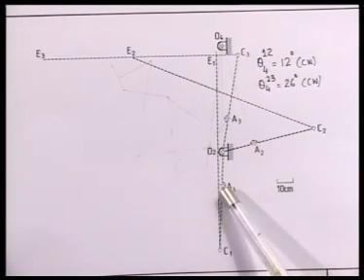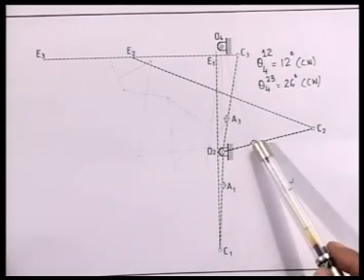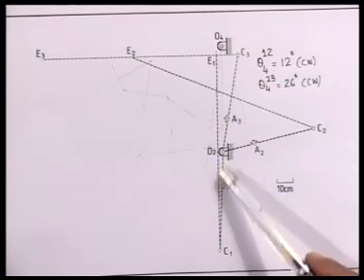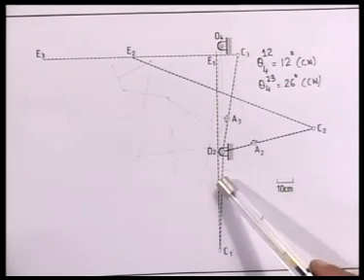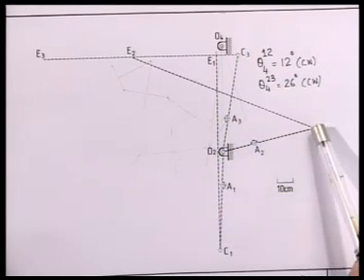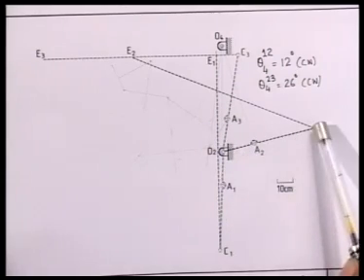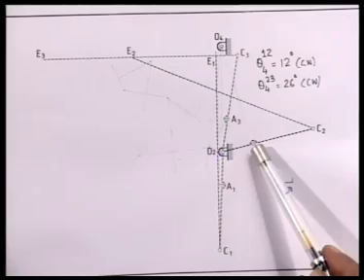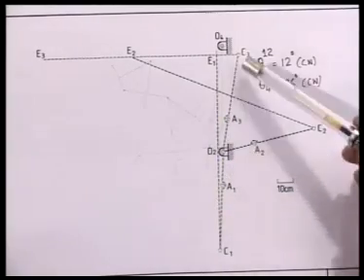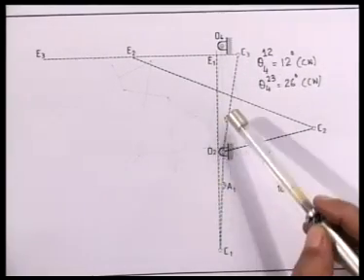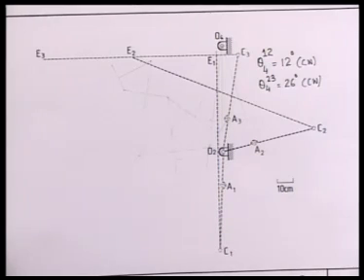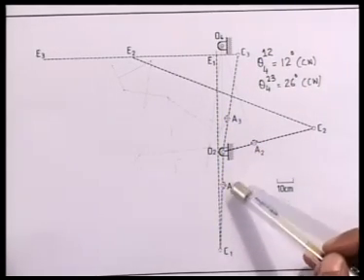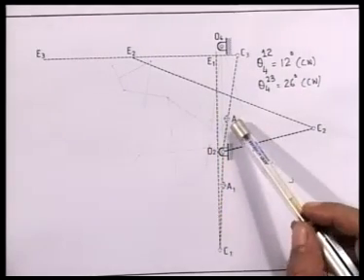So we can immediately determine where A2 and A3 are, because the distance O2A does not change. In the first configuration it is here, because C2 is given, so O2C2, this distance remains same, so I can determine A2, and O2C3, this distance remains same, so A2 comes to A3. So I know the 3 positions of this revolute pair at A, namely A1, A2, A3.